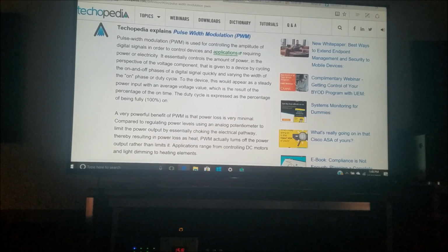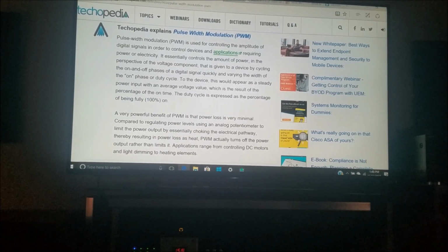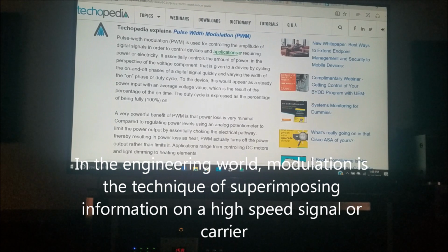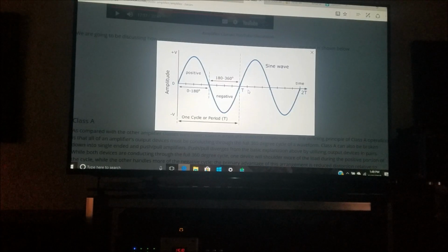It's the density and the delta-sigma modulation or related modulation technique being applied here, and it's this that becomes quite interesting. You see, the time average power value of the pulses is directly proportional to the analog signal that was coming in. After amplification, the signal is converted back to an analog signal by a passive low-pass filter this time. And well, the purpose of that output filter is to technically smooth the pulse stream to an analog signal, removing any of the high-frequency spectral components that the pulse produces.